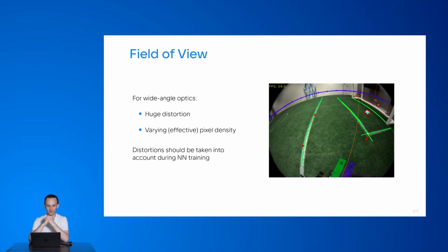One modern trend in robotics, and in particular in humanoid robotics, is wide-angle cameras. I'm talking primarily about humanoid football and other types of robotics sport. In industrial applications, of course, the field of view is defined completely by the problem that is being solved. And here in the frame you can see that this image was taken with what is commonly referred to as a fisheye lens. This is a wide-angle lens that allows for capturing objects that are very far to the right and to the left.